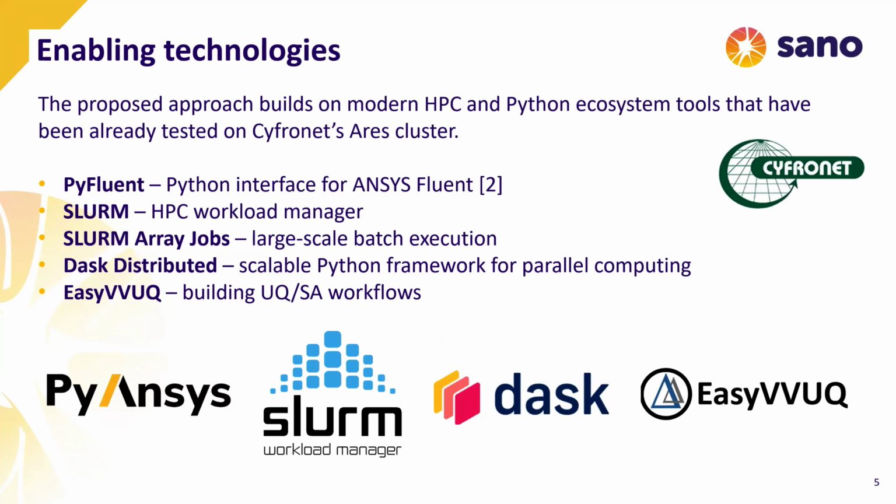To achieve this, we built a semi-automated workflow based on technologies shown here. So the approach builds on modern HPC and Python ecosystem tools. We have already tested them on Cyfronet's ARES cluster. And the most important here is PyFluent, which provides a Python interface to ANSYS Fluent. Then we have Slurm jobs. Instead of launching simulations manually, simulations are executed in batch mode on HPC resources through this mechanism.